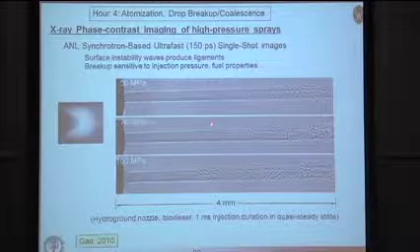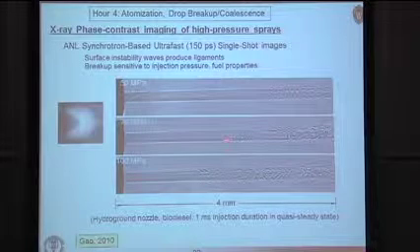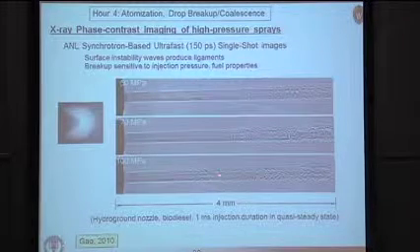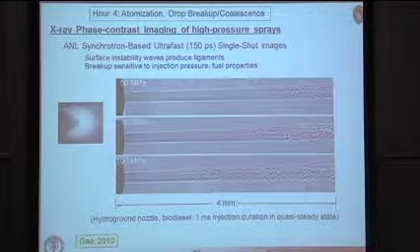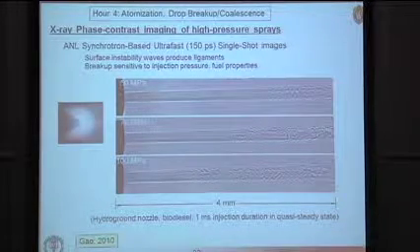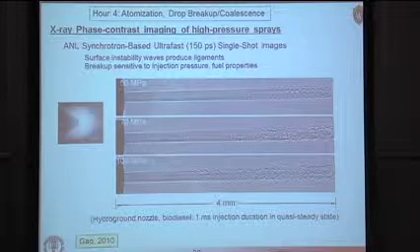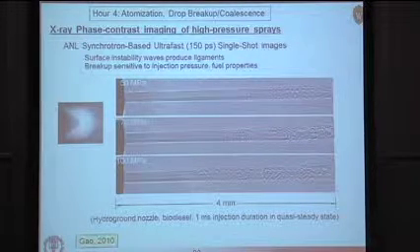And if you look carefully, you can see that there is some sort of evidence of instability waves that eventually lead to the breakup of the jet. So we take this to be at least confirmation of this concept, which, remember, you can't see inside a diesel jet. As I showed you in some of the earlier pictures, you really don't know what's happening. But with the X-rays, you can get a feel for the fact that surface waves seem to be involved. So that was very encouraging, to have a theory that is more or less validated 20 years later.